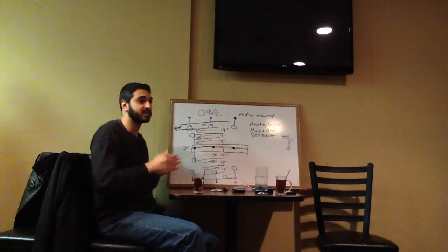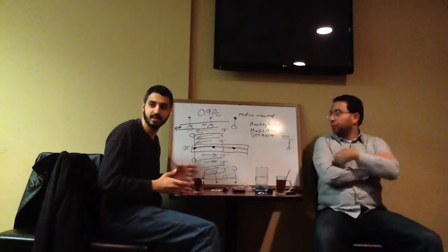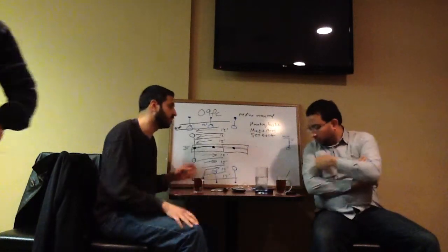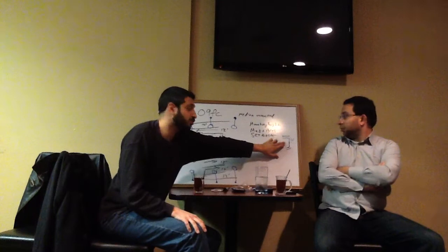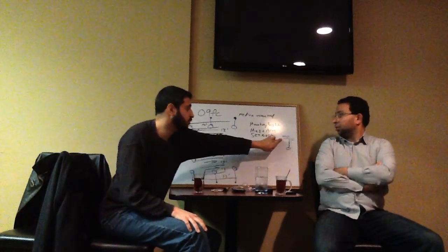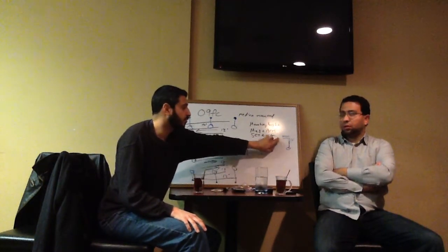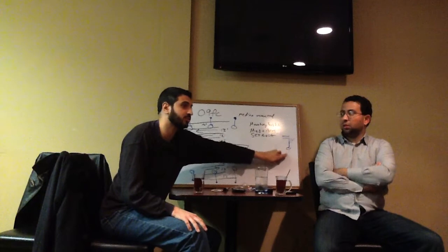So if we had something like a high mast, I would have to ask a structural designer. It becomes sort of like civil engineering, a structural design kind of thing. But that's to support the weight of the pole and the fixture. And remember also, when you're going with the arms, the further out you go, the more pressure you put on that foundation, so the deeper you might have to go.